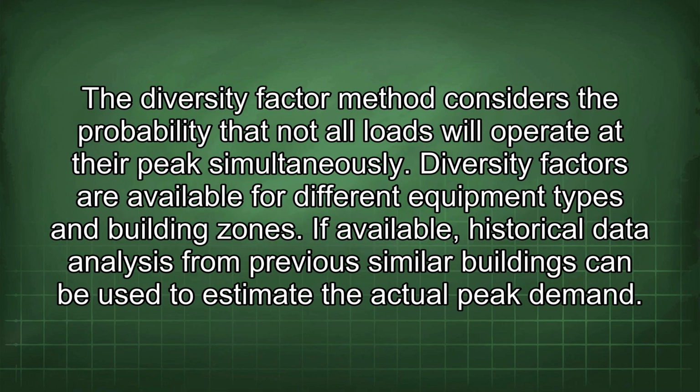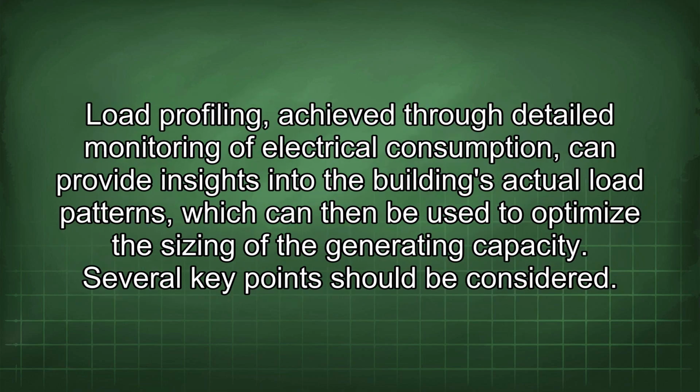The diversity factor method considers the probability that not all loads will operate at their peak simultaneously. Diversity factors are available for different equipment types and building zones. If available, historical data analysis from previous similar buildings can be used to estimate the actual peak demand. Load profiling, achieved through detailed monitoring of electrical consumption, can provide insights into the building's actual load patterns, which can then be used to optimize the sizing of the generating capacity.